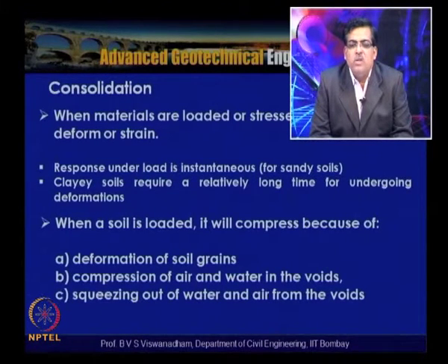When the soil is loaded, it will compress because of the following reasons. One is the deformation of the soil grains, and compression of air and water in the voids. That means the air within the voids and the water within the voids will get compressed, and there is squeezing out of water and air from the voids. These are the causes for why the soil undergoes compression.